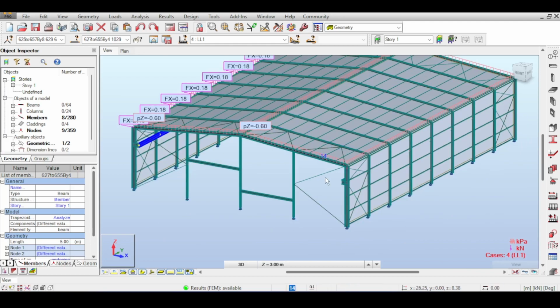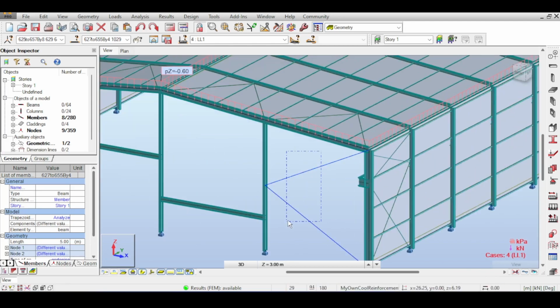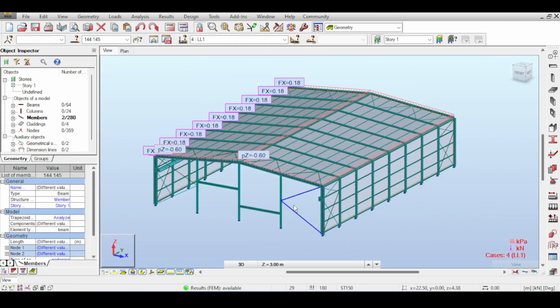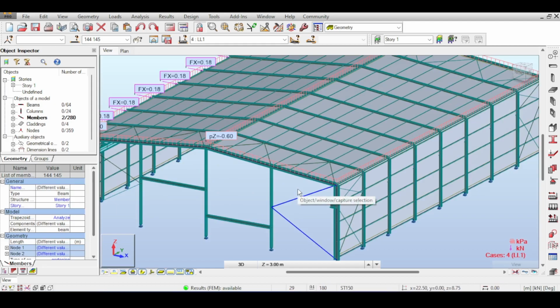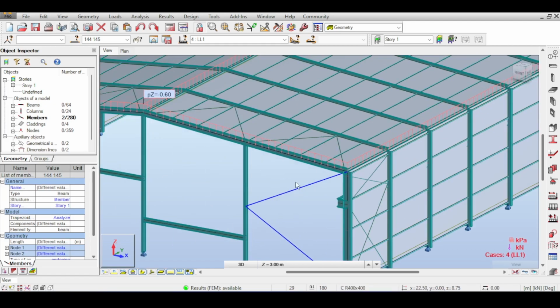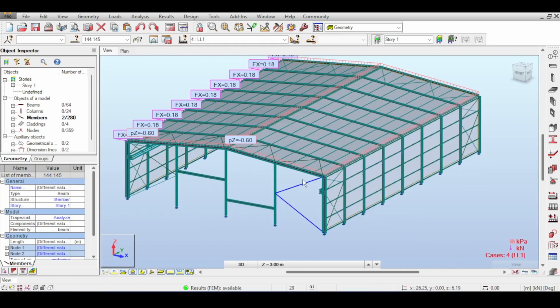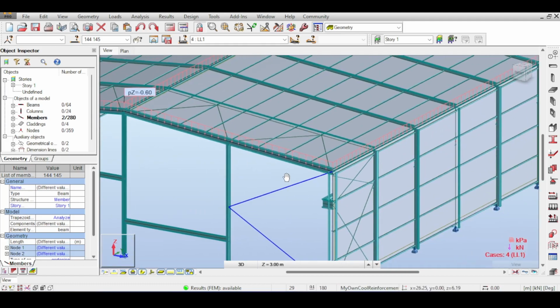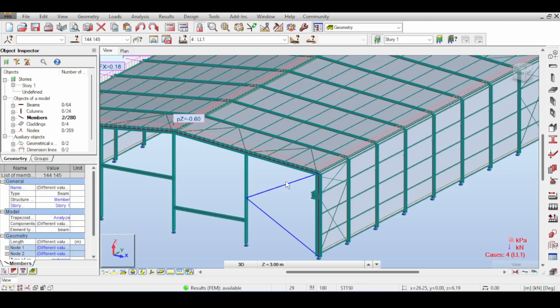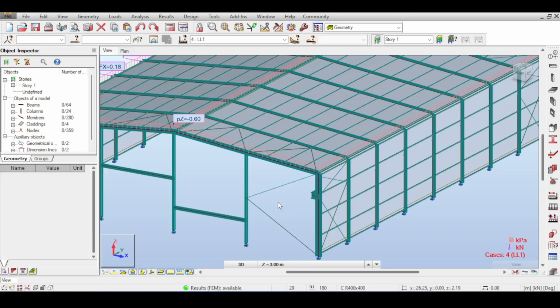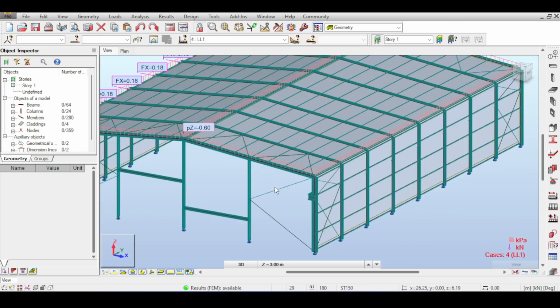That's another thing. The third thing I want to mention is that I still need to make this become a tension member. I have not done this because I wanted to consider both compression and tension members, and of course your dear viewers have mentioned that, hey, you can do that, but you need to use larger sections. I will leave it to Robot to decide because in the end he will be the one who's designing. Of course, at the design of those elements, I'm pretty sure that Robot will suggest larger sections because of the KL over r issue, which is basically the effective length over radius of gyration. So I'm pretty sure Robot will suggest larger sections.